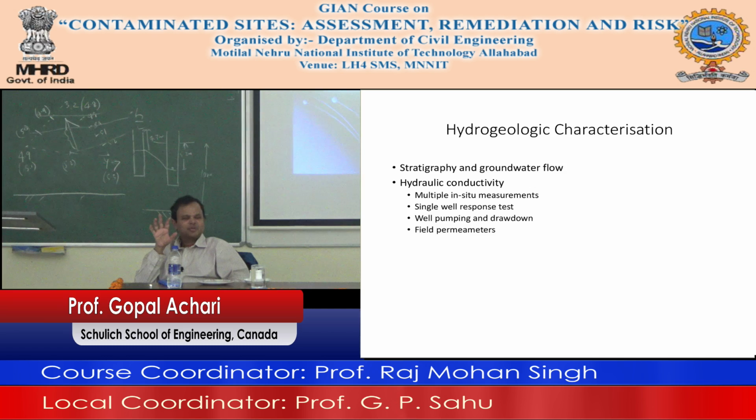So my question is a trick question, and that is why we all struggle with the term, because the origin of the word hydraulic conductivity is in Darcy's equation. Now Darcy in the mid 1800s conducted experiments. You should look at the screen at the top there and see that Q is equal to KIA, right?